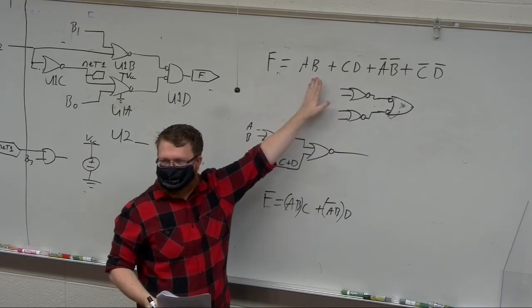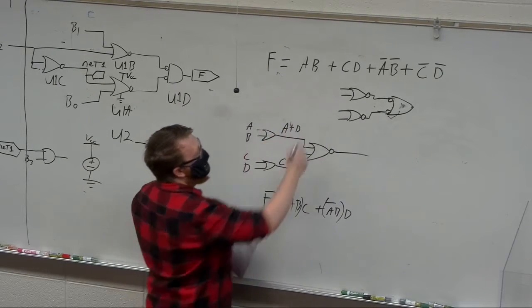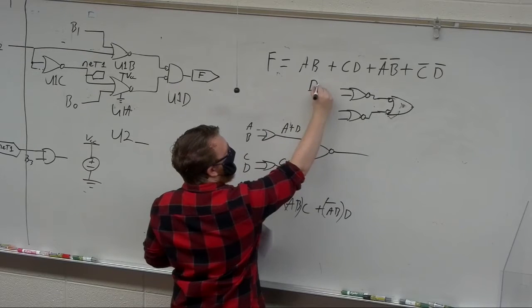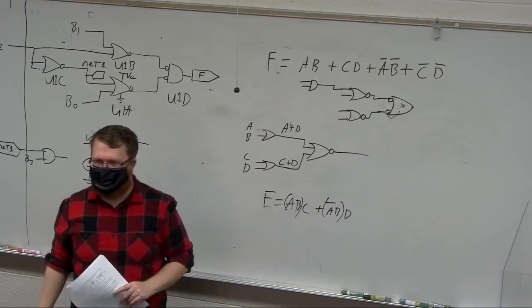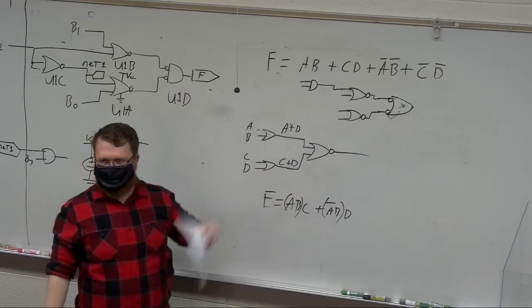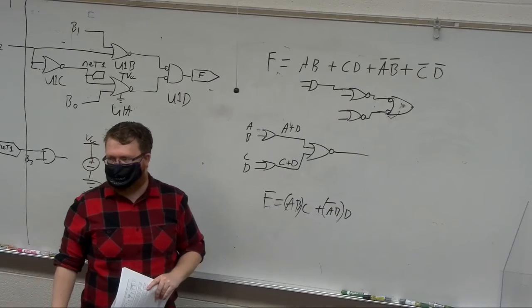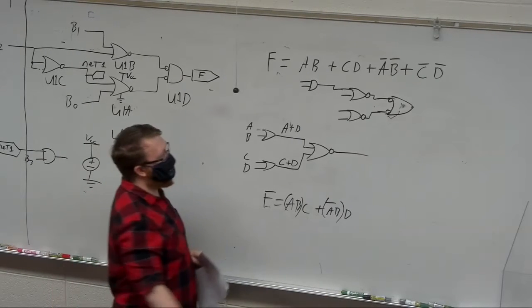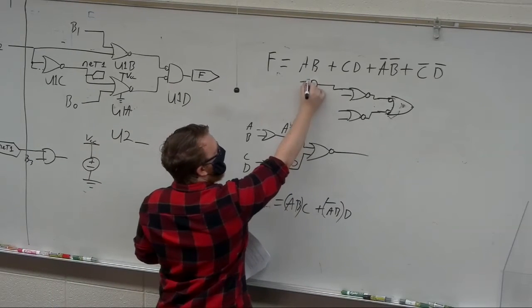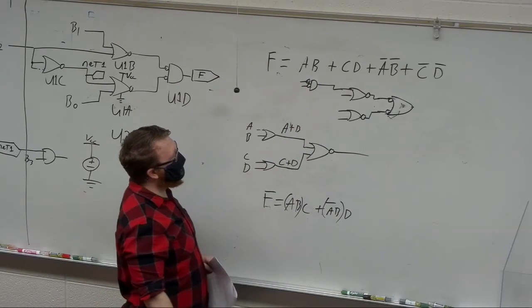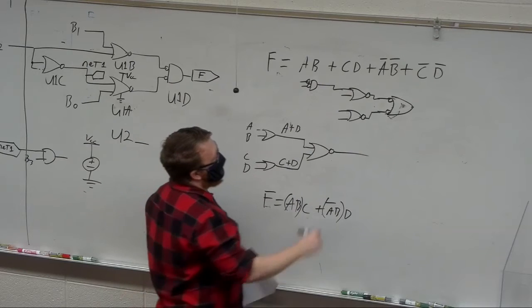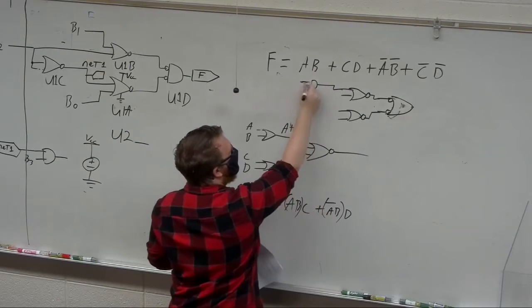Do you think you could build the rest of the circuit out with NANDs and NORs if you had to? Each of these inputs is going to be a 2 input AND gate, but you have to turn that AND gate into a NAND or NOR, which you can do by inverting the inputs, right? That is probably the easiest way to do that.